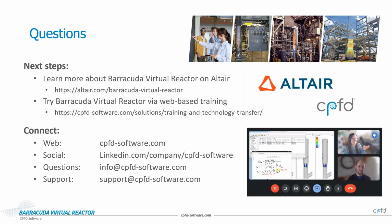But for the broader audience, we purposely don't try to compute where every particle is touching every other particle. Instead, we say, okay, a particle is going into a region. What is the probability of an impact? It cares less which particle it hit, but will it hit particles? And then you'll have various models that take over. There's a normal stress model that takes over at the denser phases. You'll have BGK-type collisional models in the more dilute phase. There are a few different ones there.